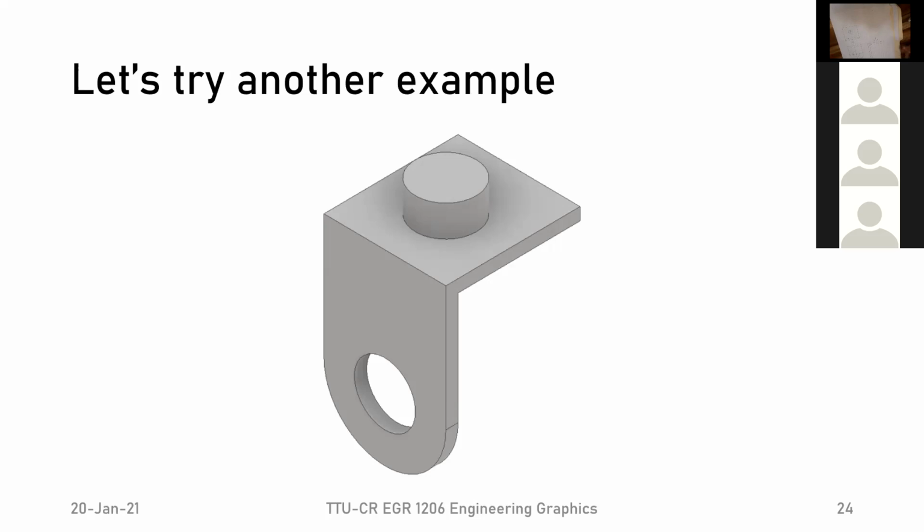So we don't have a difference, for example, from the front and top view. It's the same lines for the circle and the cylinder. So for the circle, if we see a full circle like here or any kind of arc, right, then we have to have the two center lines that cross each other. Whereas when we see just the rectangle of the cylinder, just the side view of the cylinder, then we only take the one line, right? There's not a second one that goes across here.